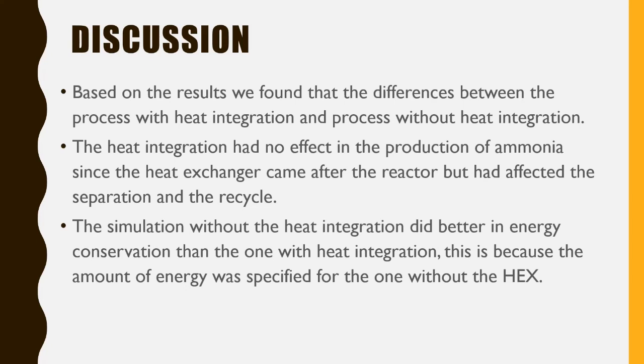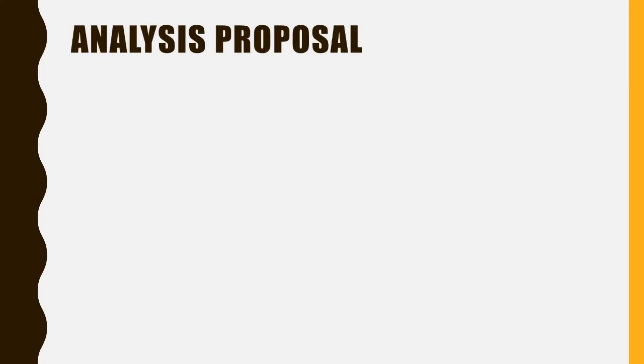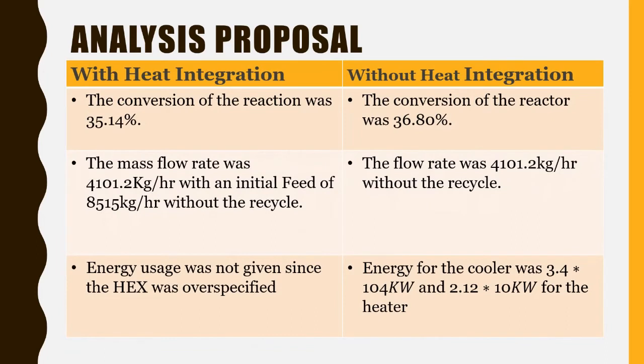Now I'm going to talk about the analysis proposal. In our simulation, the one with heat integration had a conversion of 35.14% in the reaction. For the one without heat integration, the conversion of the reactor was 36.80%. This is because of the recycle coming back and mixing with the feed, which changes the conversion of the reaction.